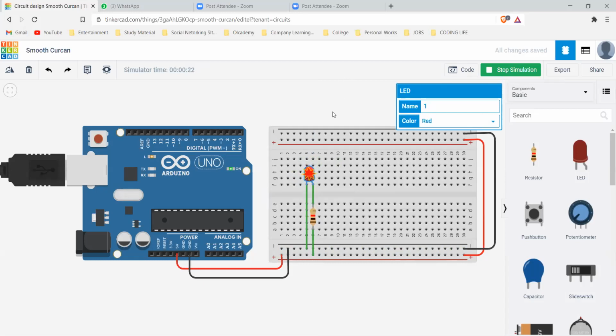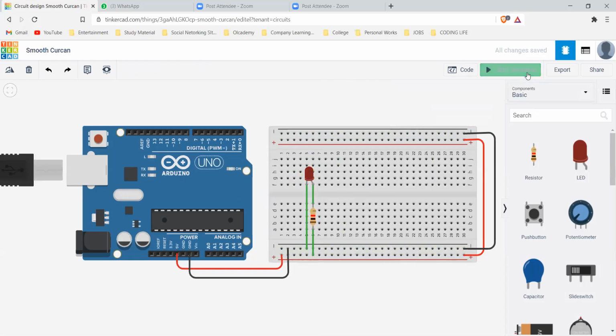And always remember, if you have to do any changes to your circuit or diagram, anything, you always need to stop the simulation before you do anything else. Always stop your simulation and then only visit or do any alterations to the code. So without wasting any further time on these basic circuits, let us take an example of a circuit that not only includes the input and output, but also things that we can analyze from the environment.